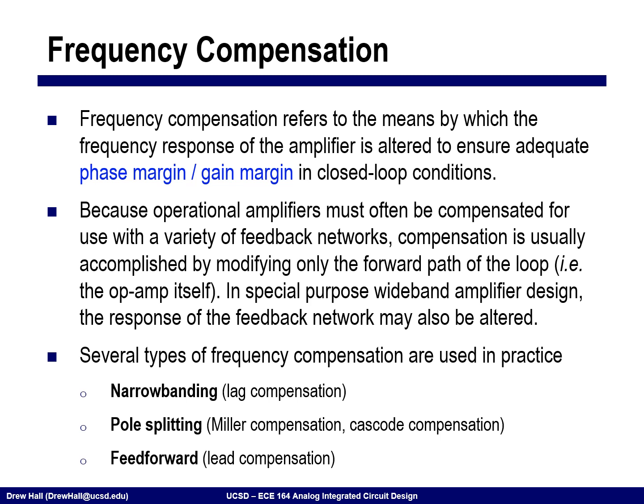All right, so now we get to the notion of what's called frequency compensation. So frequency compensation is all about managing the frequency response such that when we put this amplifier in feedback, we know where all of the poles and zeros are. Okay, and so oftentimes this is talked about in terms of the stability criteria. Okay, and so there's multiple ways of looking at stability. We'll talk about them in the feedback lecture next time. Two typical ways that one would assess stability are the phase margin and the gain margin.